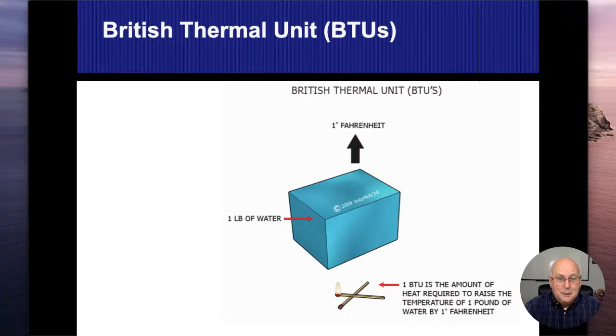So on my website, thehomeInspectors.com, if you go under education and employment, you're going to find a link to a gas timing chart. Basically it measures in seconds how long it takes one of those dials to spin around, whether it's half pound, full pound, whatever. And each one, however many seconds it takes to do one full revolution, correlates to how many BTUs of natural gas are being used.